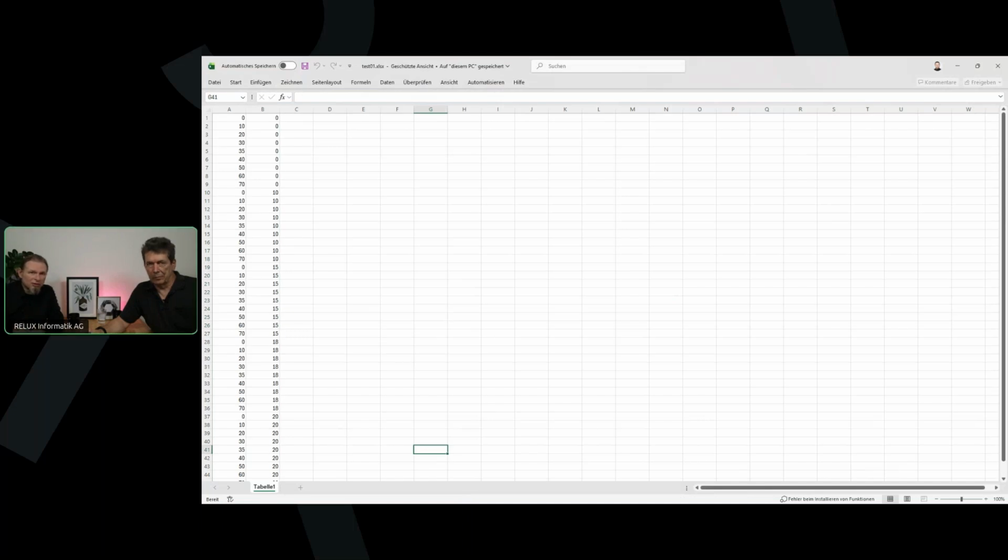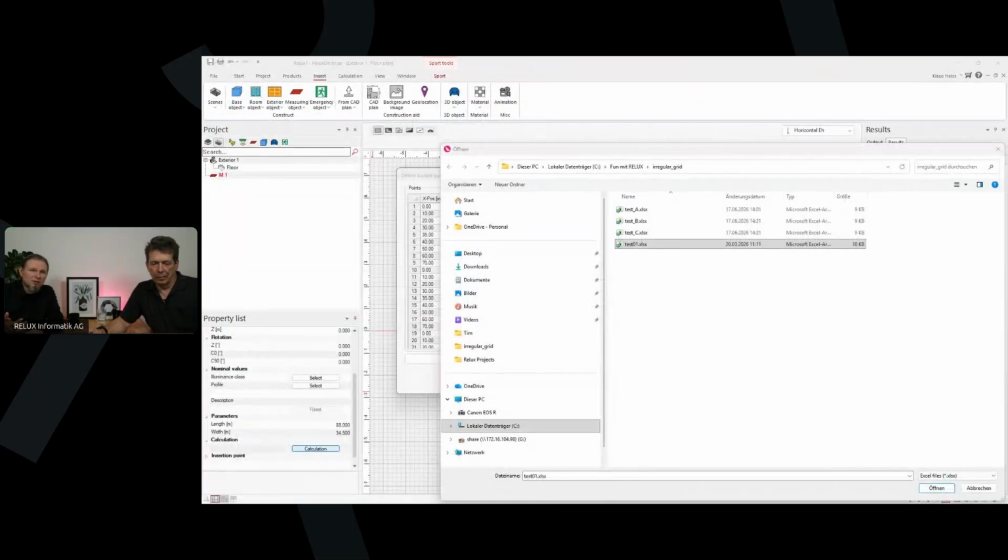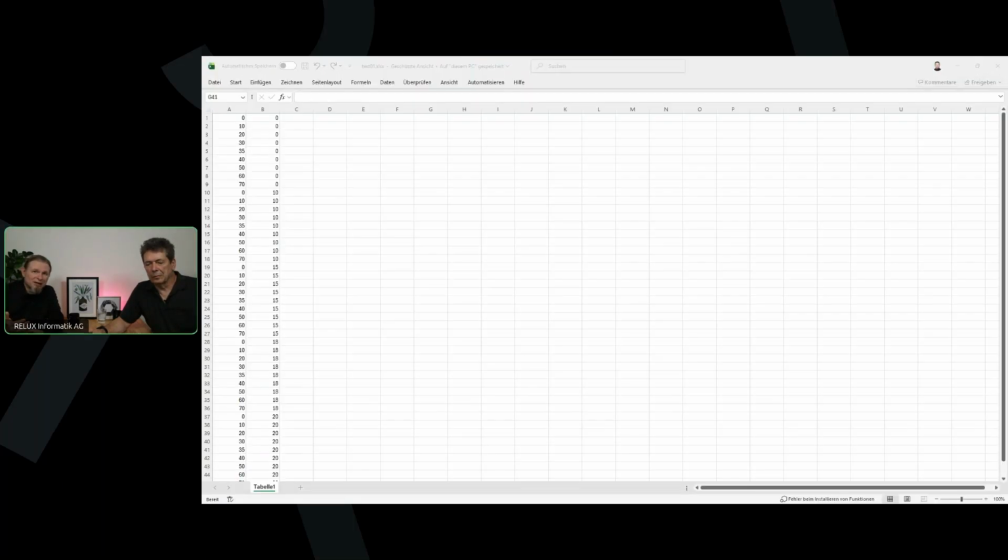If we change this, so if we have some grid points in this corner, some grid points in another corner, or we are just messing up the covering of grid points in the area, then we cannot tell that the area has an average illuminance. It's not possible because the points are not equally representative. We can say the calculated points have an average, that is still possible, but then it's not representative for the area. The points themselves have an average, but it no longer speaks for the area. We will show this in a short example.